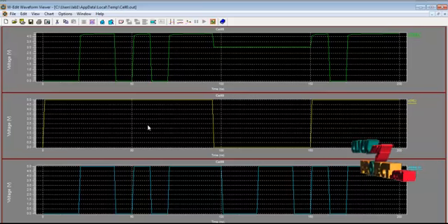This is the activation process. This is the deactivation process for the write signal. When the write signal is deactivated, whatever the data input, it is not applied and the stored data is read as the final output. When writing is deactivated, whatever the data input, the process does not write and the cell holds its previous state. These are the final results for our architecture.